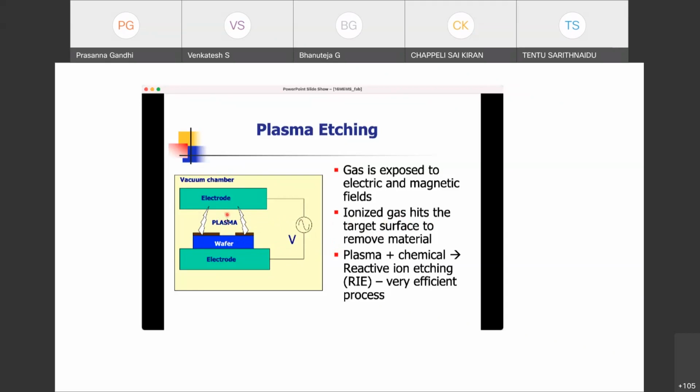or plasma etching, so to say. And it is only in the vertical direction, or a particular direction, because the voltage is applied between these two electrodes. So the motion is along the vertical direction for ions and electrons, in an oscillatory fashion because it's an AC voltage applied here. So these are machines that are available for such an etching process. Now you can introduce some gaseous species which chemically react with the wafer surface. Then it becomes reactive ion etching. So now the ions are not only bombarding the surface, but they are also reacting and producing some reaction products during the process.